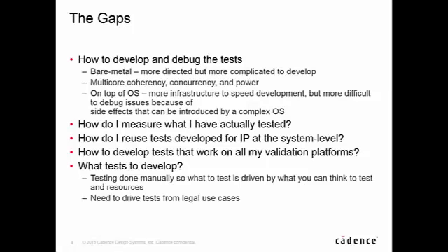We really want to drive tests from a legal use cases perspective, because as you get to the SoC level, the number of illegal test cases becomes larger, and if you spend a lot of time generating tests that are illegal, you extend your verification time any longer than is necessary.